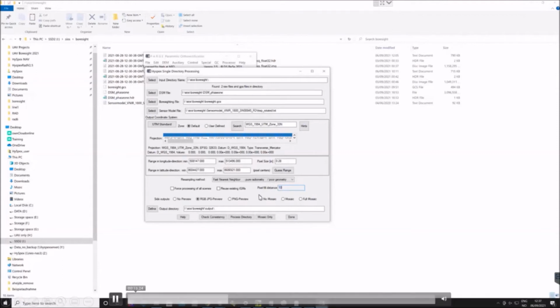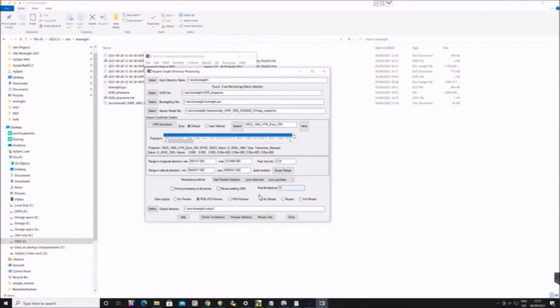I think you should pause. You were a bit quick there. The DSM you're using is generated using the Phase 1 images. Yeah, in Pix4D. And what resolution does that have again? I don't remember. Yeah, it has 9 centimeter ground resolution. So it's a very good DSM to use for a Boresight here. But I guess we're coming back to that as well. For the area where we are processing afterwards, we only have the 5 meter resolution, right? Yes.